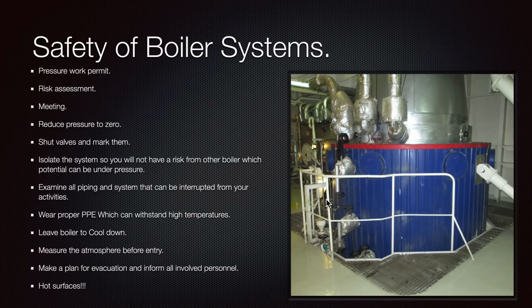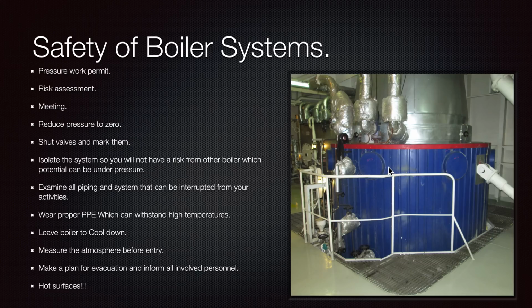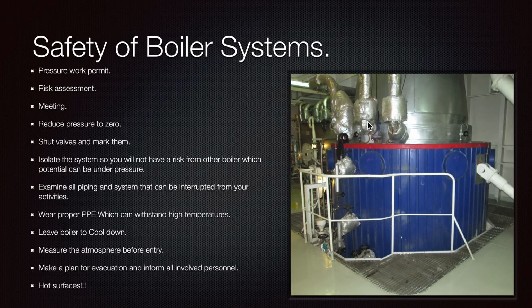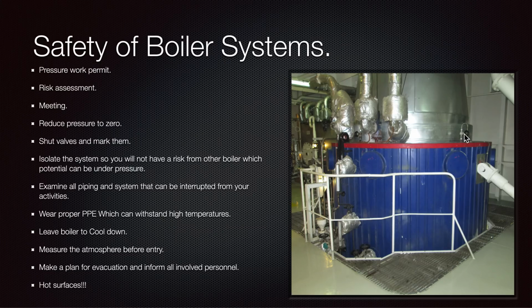And dealing with the boilers, we are talking about high temperatures, and even when the boiler has been depressurized for 1 or 2 hours, the temperature and the heat are still present in the materials and the metal piping. So leave the boiler to cool down for 1-2 days, and later proceed with the checks, then slightly open the drains, check, isolate everything, open the vent valve here on the top, and look if everything is depressurized and cooled down.